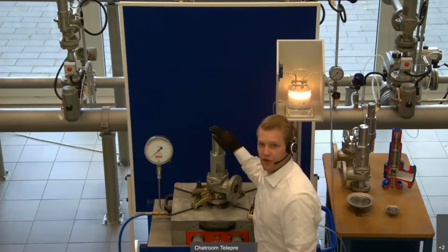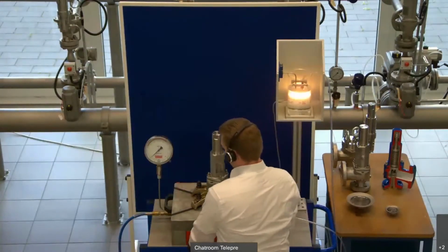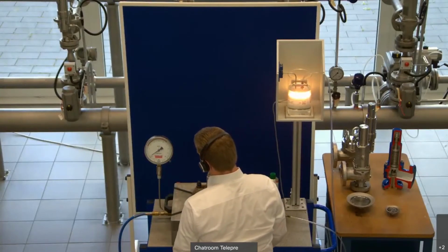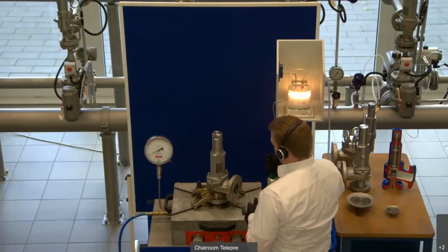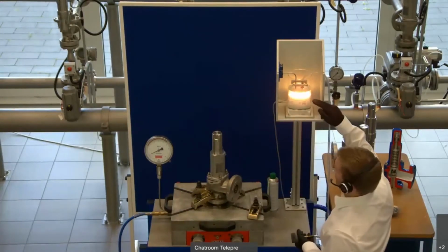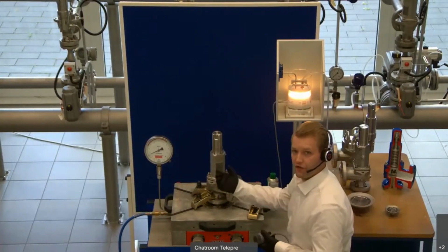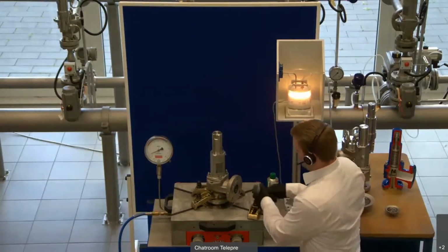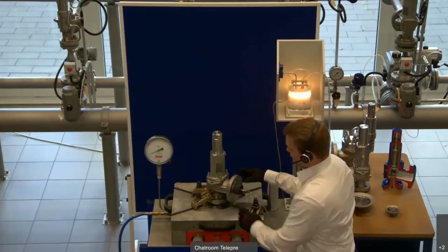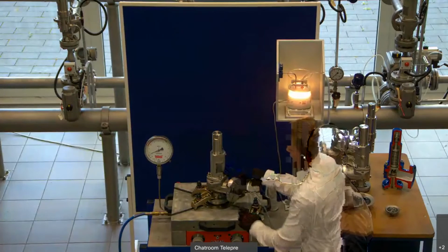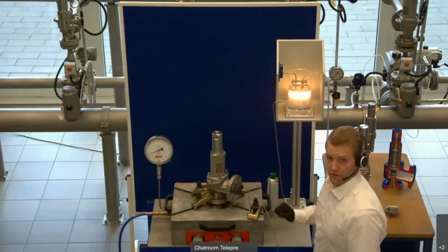Our set pressure is 3.5 bar G. You will see where our initial audible discharge is. Be careful on your test bench: do it the other way. First go to the initial audible discharge, and only after this do you go in with your rubber plug here.